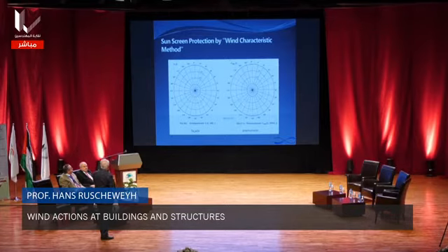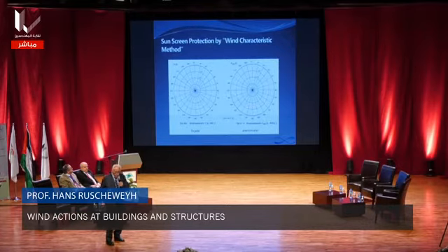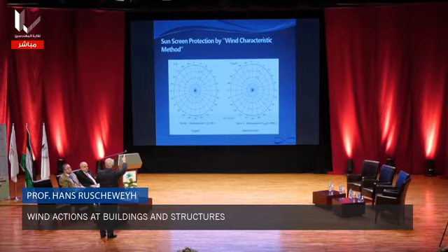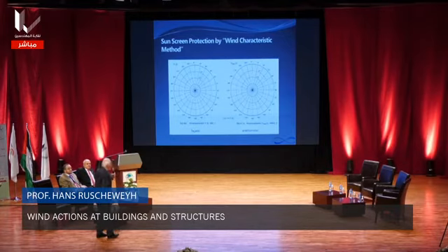So we have then in the northwest direction a high attack of the wind. Also in the east-south direction, but on the north side, on the north and the northwest, also on the south and southwest, you have less wind action. That means that at that point, the sunscreen would be pulled up only when the wind is coming from these directions, not from the other wind directions.